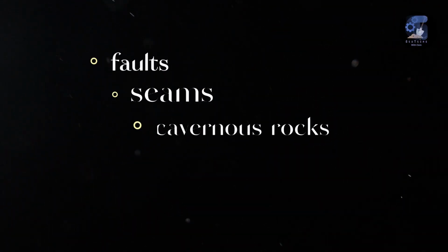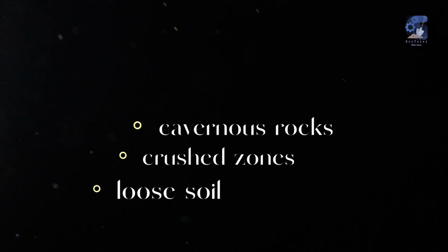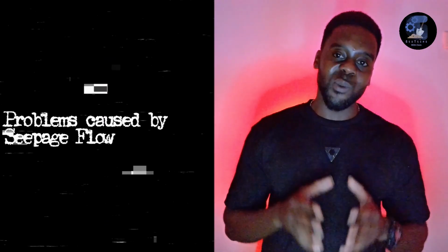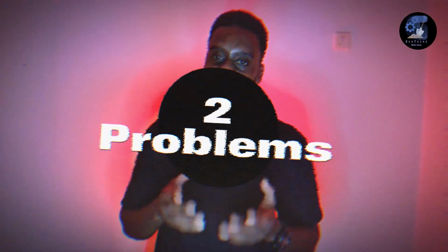However, the real conditions of a geological site may say otherwise. The site usually has faults, seams, carbonaceous rocks, crush zones, and loose overlying soil, which compromises the stability of the dam and the foundation. The imperviousness of the foundation is very important to minimize seepage flow in both soil and rock foundations. When the foundation consists of pervious sands and gravel such as alluvial deposits, two possible problems exist.